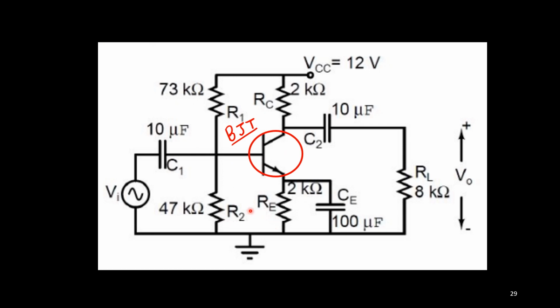This is the purpose. And then to connect this input voltage to this amplifier, we will use this capacitor, which is called a coupling capacitor, and another capacitor C2 when we use some load with this amplifier. So these are two coupling capacitors. Because of these two, we can get some bending in the low frequencies that I have discussed. Along with this, there is one more capacitor externally connected across RE. This is called a bypass capacitor, right? This circuit will be discussed in detail, but here we will be discussing the model for this BJT in detail. This is the main aim of this video.